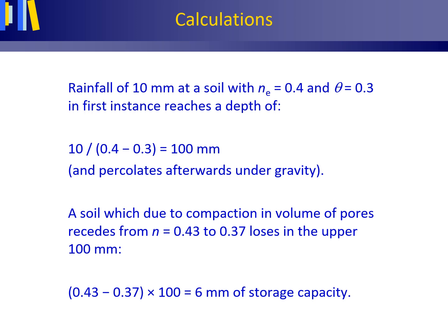This sheet introduces some typical calculations for the soil water zone. The effective porosity Ne is the volume fraction, or percentage, of soil or sediment that participates in the water flow process, thus excluding dead-end pores.